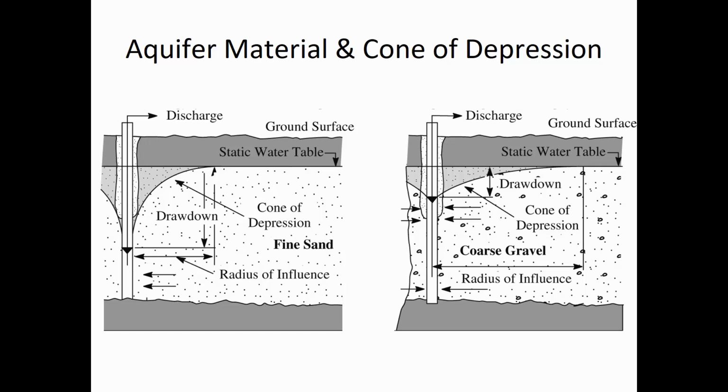Okay, so how do you achieve a certain flow rate? If you have a low K, low hydraulic conductivity, you need more delta H to force the same amount of water. So here, the driving force is the elevation differential between the water depth in the casing and the water depth at some distance away, like 10 meters away. That's going to be the driving force. And so you don't need as much driving force because there's less friction through the gravel.